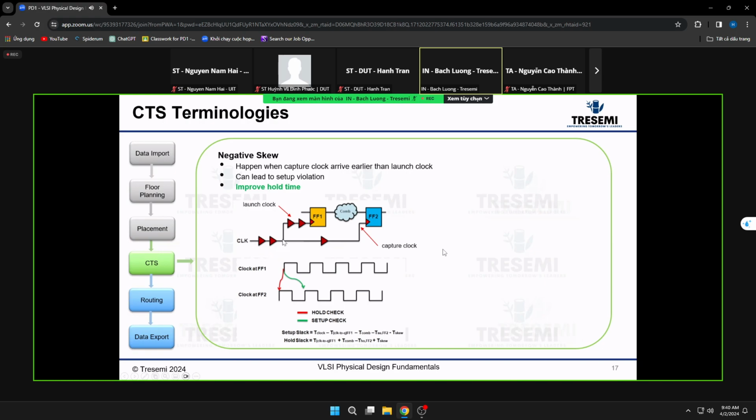This will be removed from the timing calculations, because launch and capture can't have different timing on the same path. Yeah, so that's a good question from Kanyu. In your lab, we do have the CPPR on, and in the timing reports, in the detail and the summary, you'll see that CPPR is adjusted from the skew.